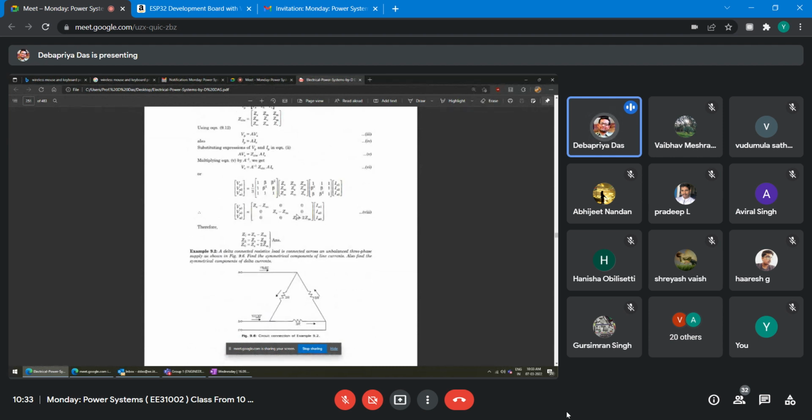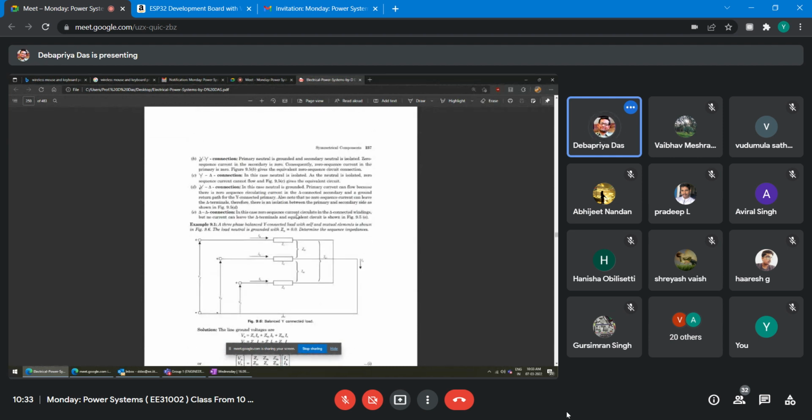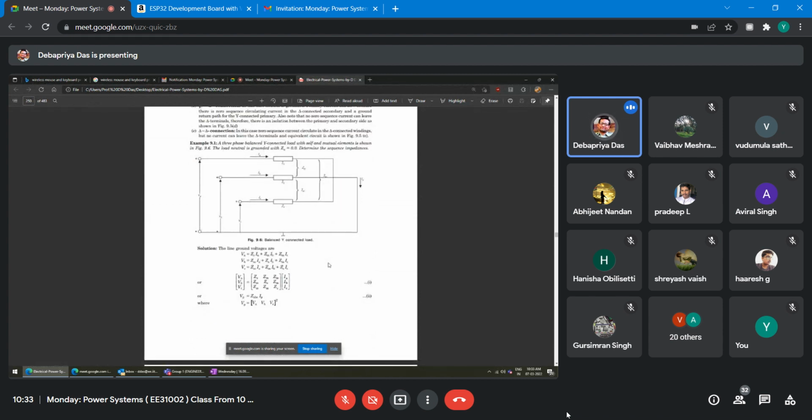In our electrical engineering, there are many such interesting things, right? For easy calculation, generally in electrical engineering, except for fault studies, wherever necessary you use the Y matrix, right? But for fault studies, we use the Z matrix due to computational efficiency, right? And nowadays, many packages are commercially available. Still, many things may not be available, and many software packages may be available. But when you bring in software, it has to be tested very, very carefully.